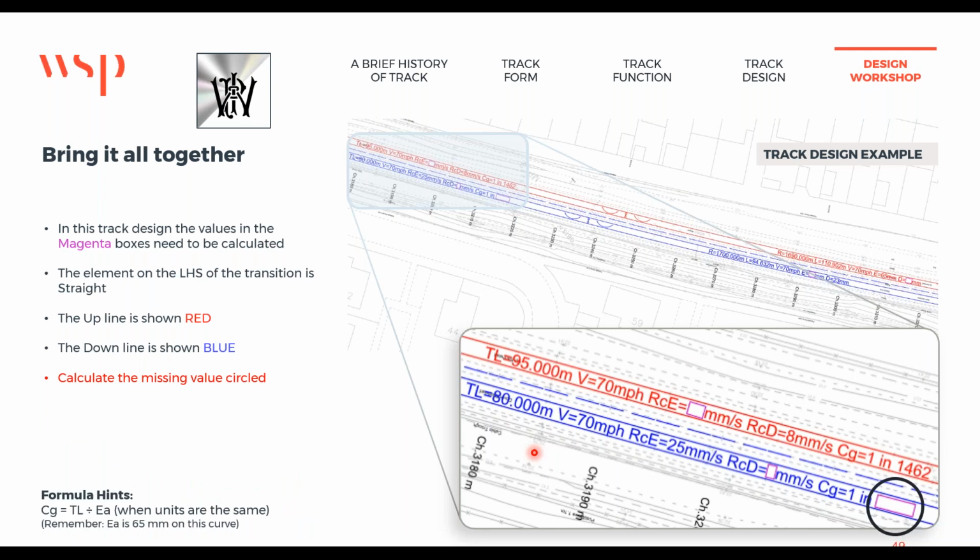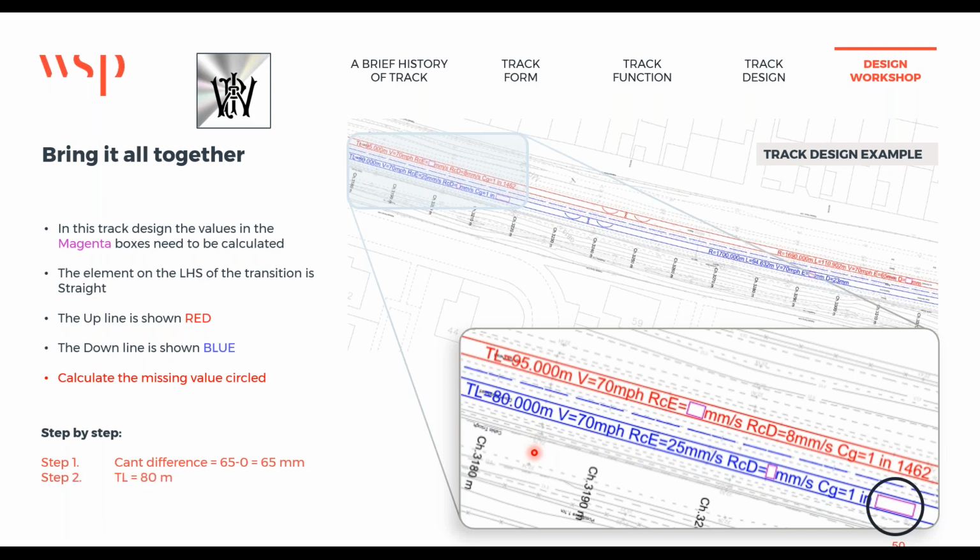Okay, last one. Cant gradient, 1 in something. Step by step for the cant gradient. Cant difference is 65 minus 0. We know it's 0 because the other bits are straight. The transition length is 80. Cant gradient is the length divided by the cant, in the same units. 0.065 meters is 65 mil, and it's 1 in 1231. Or you can do it another way, keep it in millimeters: 80,000 millimeters is your 80 meters, keep your 65 as millimeters, it's still 1 in 1231.